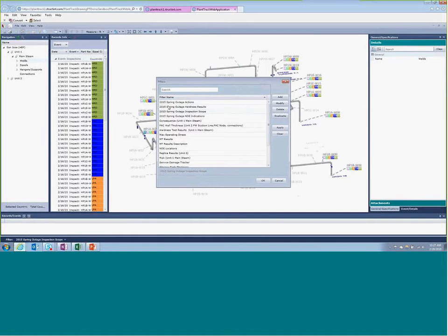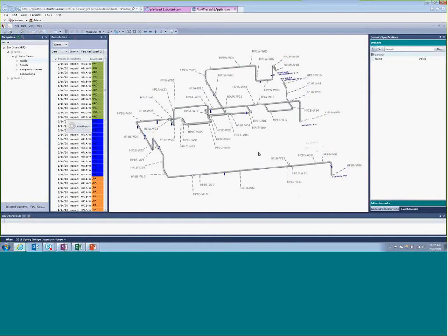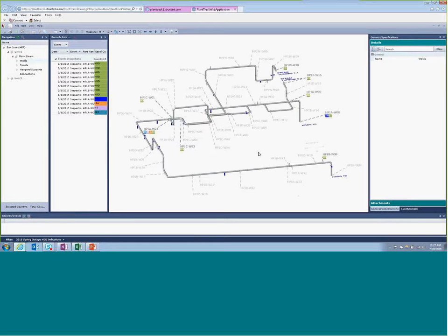So again, I can come here and say, ignore 2015, this is arbitrary. So I can come through and say, show me the 2015 spring outage NDE indications. Okay. So now what we see is we have a couple of welds that came up with hardness flags. Grade 91 hardness is a really important method to utilize to assess the state of that particular material, whether or not it was maltreated. So you see that we have a couple of welds that came up as a flag with hardness testing, and then with two welds, this weld 24, which was that problematic one, just knowing that's an industry issue on my behalf. So it actually was a problem, and then we have this particular one, where I'll touch on that in just a second.